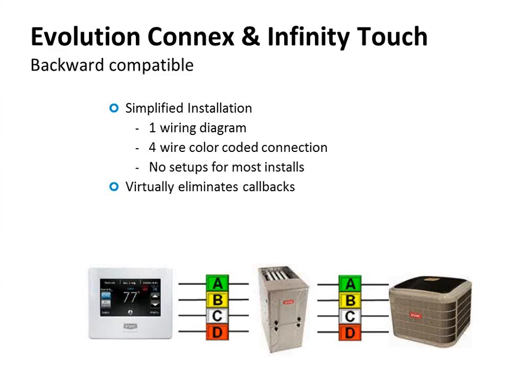The outdoor units can be communicating or non-communicating, and we do a whole 4-hour class on how to install these stats and these systems. But for today's purposes, we're going to assume everything's communicating, furnace and outdoor unit. Outdoor unit meaning AC or heat pump.